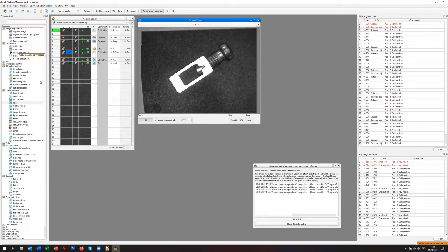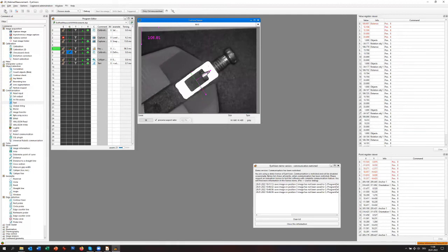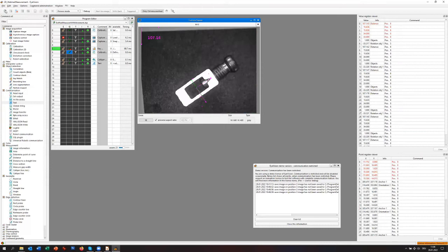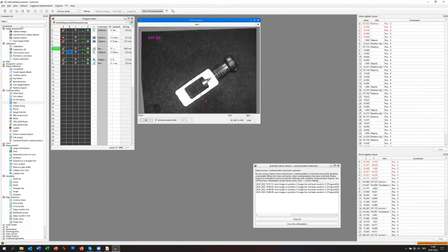Today I want to do the simple calibration, and the simple calibration normally is based on the measurement of the part. That means, for example, you use a real caliper, or you use a golden part, as I showed it to you. Here you see now my caliper, and my caliper says this is 4 millimeters. This is 107 pixels or 106, and we could use this to do a simple calibration. Why do we have this 106 and 107?